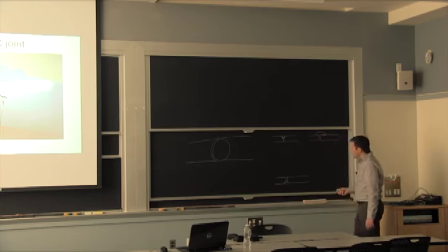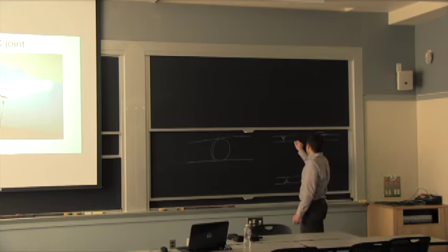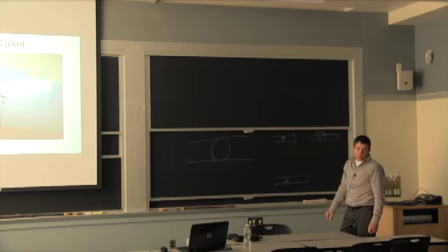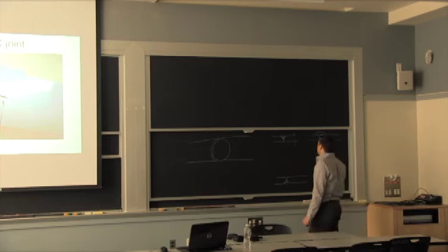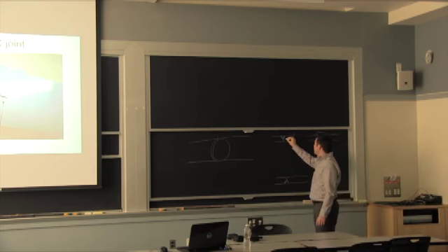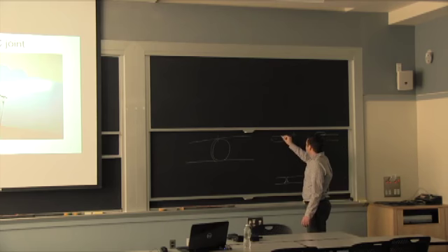The other thing you're trying to achieve, if you made that pipe a certain thickness, this is a schedule 80, so what are we looking at? Probably 1/4 to 3/8 of an inch. It's very thick. There was a reason. You wanted it to be strong, but if you're loading it in tension in this direction because of bending in service, you'll have a notch. If you weld this the way it's done there, and maybe I shouldn't even try to reproduce it, but it's something like this. There you go.